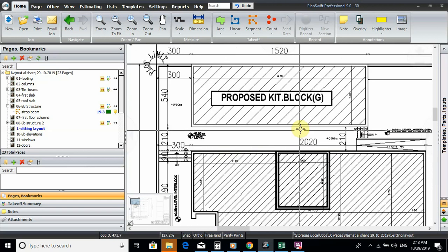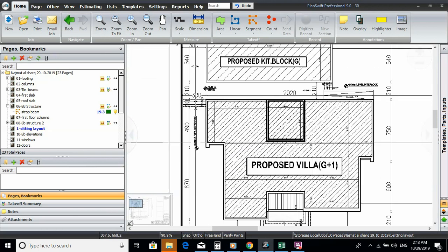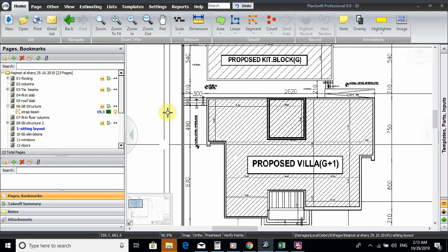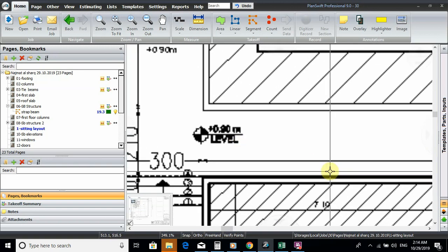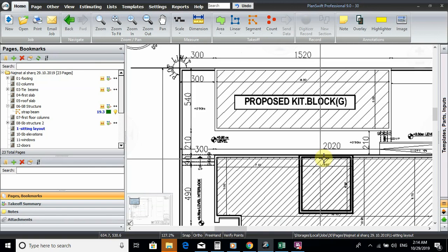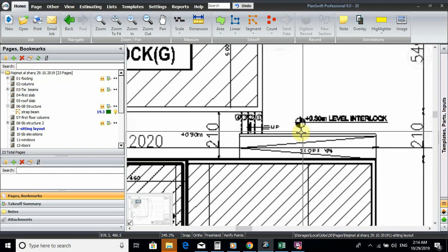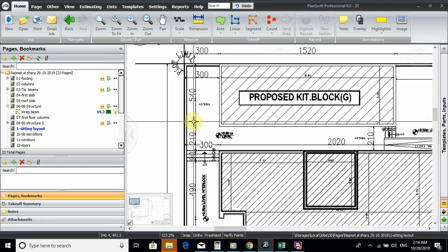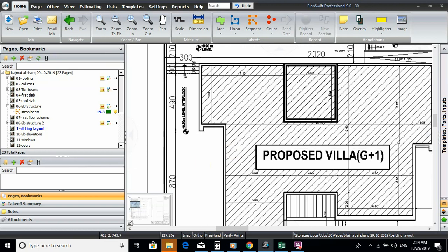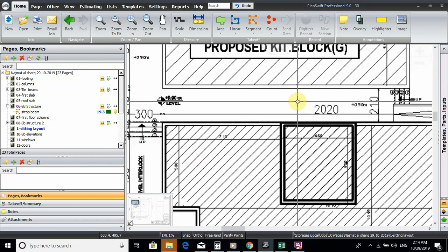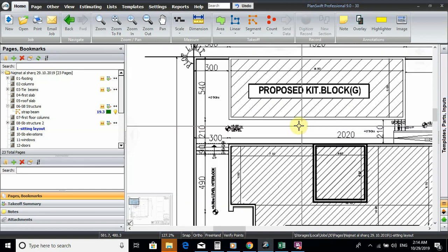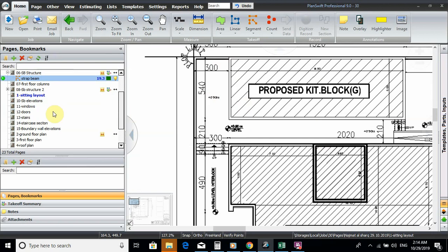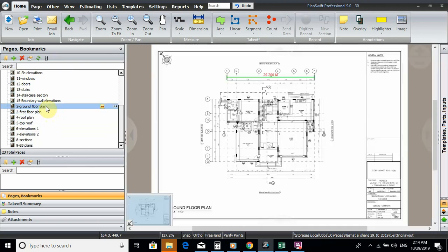We will take the common external entrance. This is normal interlock. See, normal interlock. But there are steps here. So there is a common entrance that has to be cast in concrete between the both. Though sometimes they just do backfilling and make it like the interlock. But 99% of the time we will make the common entrance in concrete. So we will take the area from here because it's not indicated fully in here.